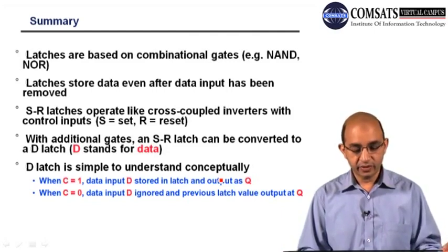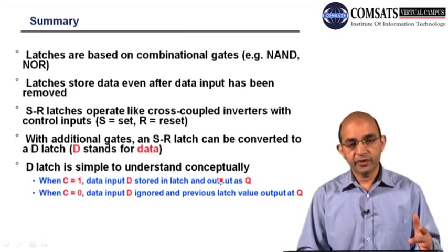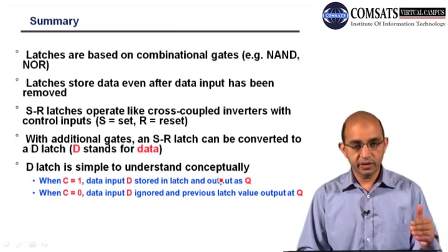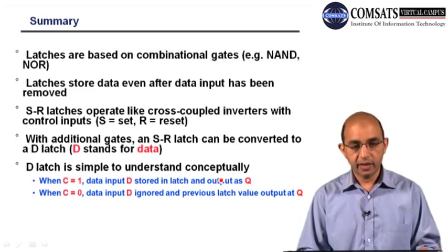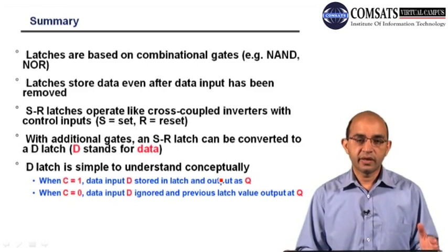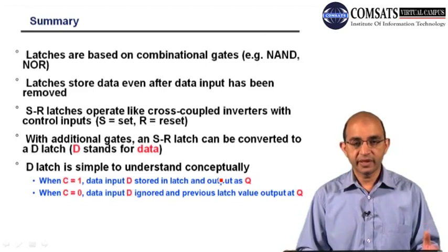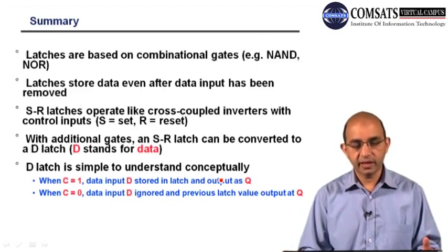Latches are the basic building block for sequential circuitry. We discussed the SR latch, in which we cross coupled the gates. With NOR gates, we cross coupled them and introduced two input signals, one for set and the other for reset. But the problem with SR latches is that we came across race conditions, which violate the basic principles of digital logic design.